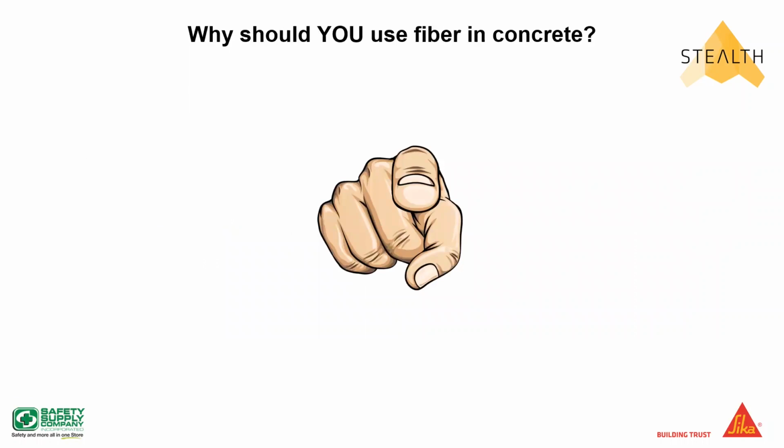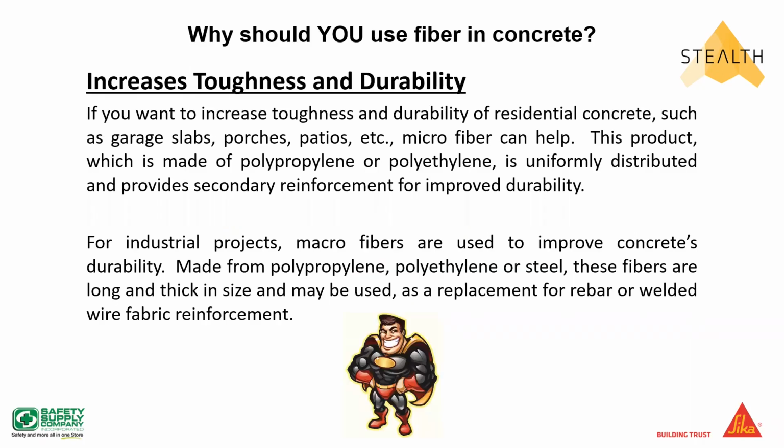So why should you use fiber in your concrete? One thing it does, it absolutely increases the toughness and durability, whether it's a residential project that you might be working on or an industrial project. You could have a need for micro or macro on either. Just because it's a microfiber does not mean that it's always going to be used in just a residential application. We use microfibers in industrial, commercial applications, just like we use macro fiber in residential applications.